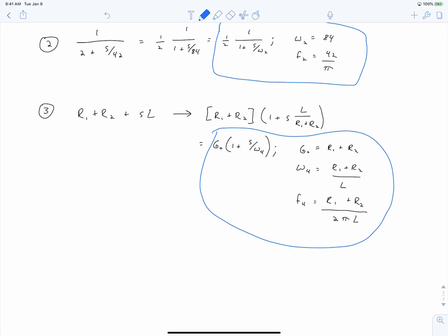And what we're doing here is we're setting the stage for being able to say, hey, I want to have a transfer function which has a zero at the frequency given by f4. And I'm going to realize this with two resistors and an inductor. What should be the values of my resistance and my inductance in order to get a zero at the frequency f4? So this is now going back to the backwards problem, or the inverse problem. We're trying to build up a set of tools that allows us to specify a desired transfer function, which is going to be our controller, and then figure out the circuit components that are needed to make that transfer function within our circuit. So that is the task of an engineer, time and again, is to know our analysis tools, which brings us from circuit elements forward to a transfer function, but also to be able to invert the problem and go from a desired transfer function to our circuit elements.